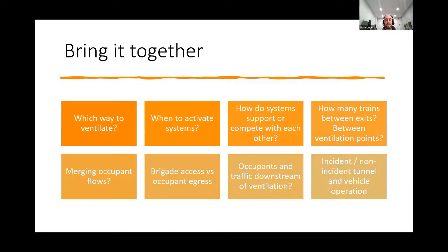There are some different mindsets. The projects I've worked on have mostly been activated as soon as you can, but there are some other mindsets of don't activate it until after evacuation, because you might want to let the smoke layer stratify as much as possible so that people can escape underneath. That has a big role.